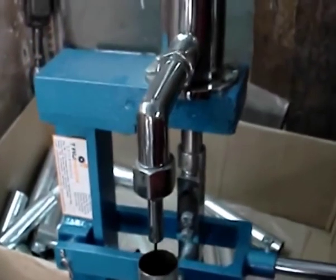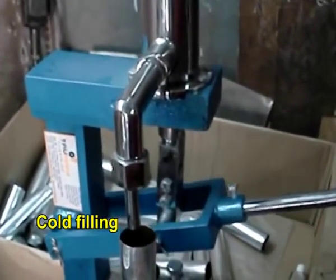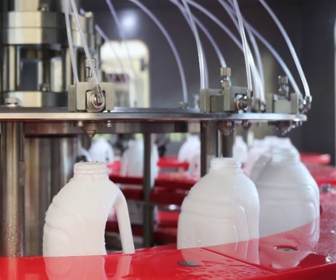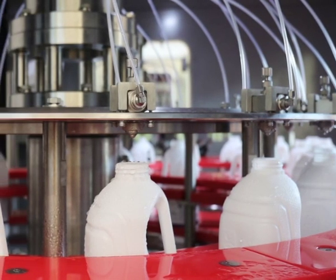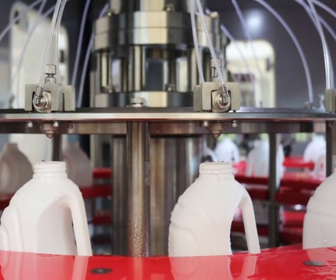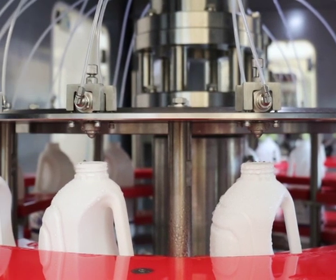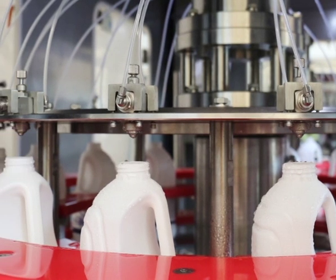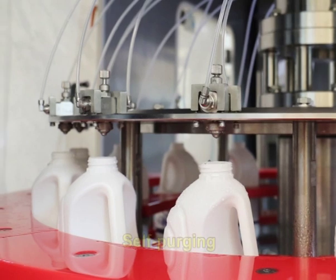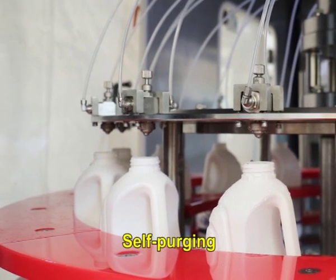There are two filling methods, cold filling and pressure filling. In cold filling, both the product and propellant are refrigerated and filled volumetrically as liquid through the 1-inch aperture before the valve is swagged into position. This process is self-purging.